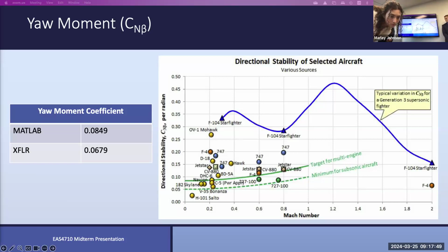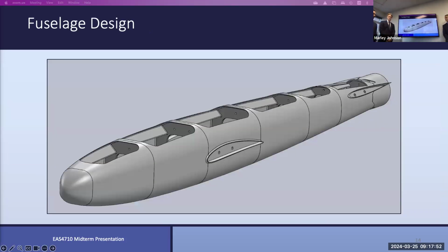Yes, about this one. You have so many openings on top. I mean, is that really necessary? Well, we have a lot of components, with all the camera stuff we're going to add and making sure landing gear is implemented correctly, we just don't have access from the top otherwise. Every time you open something for structure, you weaken structure. Also, we did test this with one of our test sections. We actually cut out an access hatch, and we did see that cutting out the access hatch on top didn't affect the structural strength that much.